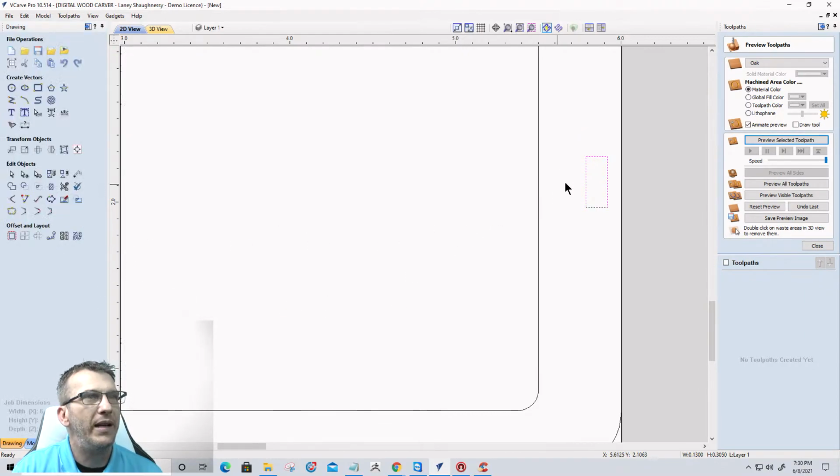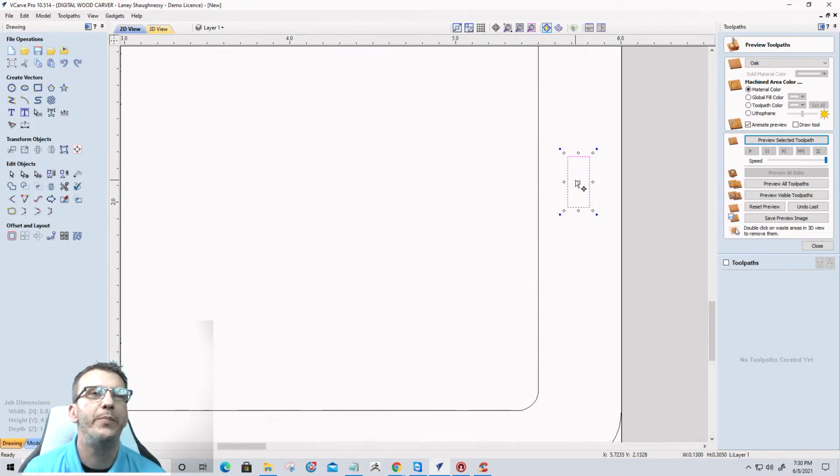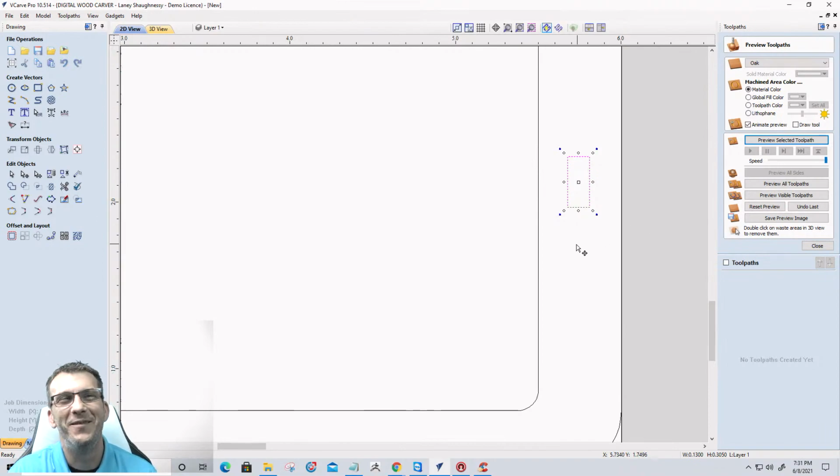And this little opening, when we cut it with our 1/8 inch end mill, our end mill will be able to go in there and do a slight little pocket. We're going to go down about 0.26 inches deep, to give us a little bit of playroom. John did some homework and testing, and when it gets milled out, it's going to be a very nice fit for a 1/4 inch by 1/4 inch by 1/8 inch square magnet. So thank you, John, for doing that for me.